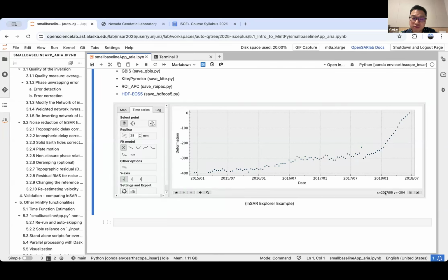And also, if you have a fault, for example a structural fault, and you know there's not much horizontal deformation perpendicular to the fault, then you can specify a direction of the horizontal deformation. And then you can decompose your ascending and descending result into vertical and fault parallel deformation. That's also a very valid and reasonable decomposition.